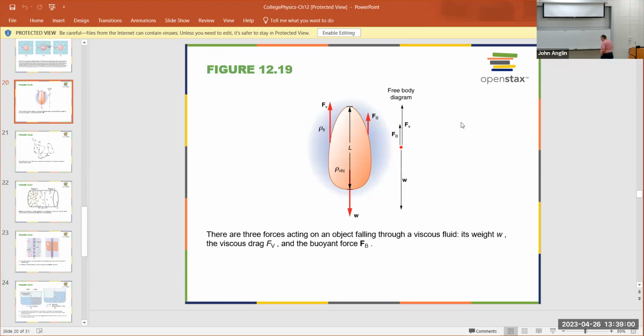Now, that is a very, very complex problem because the vehicle is re-entering the atmosphere where the density is very, very thin. And then as we get lower in the atmosphere, the density increases and it's not a linear increase. So that becomes a pretty nasty problem to do, to find out exactly what the angle is such that you can slow down enough to deploy the parachutes to land at a particular spot. But it's using exactly this principle.